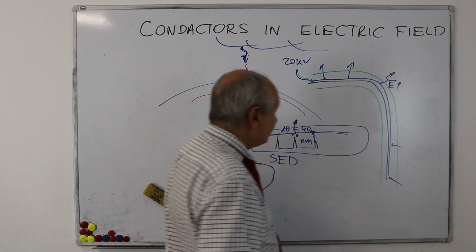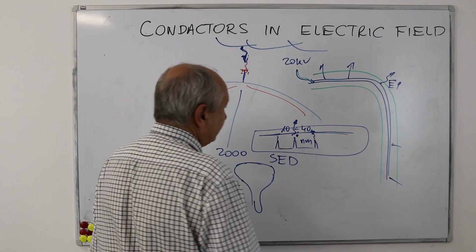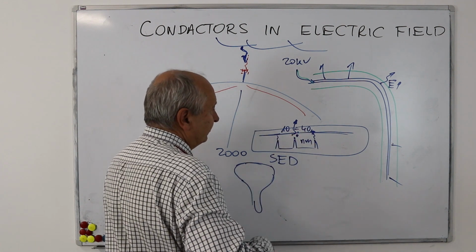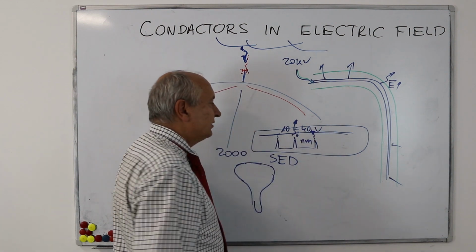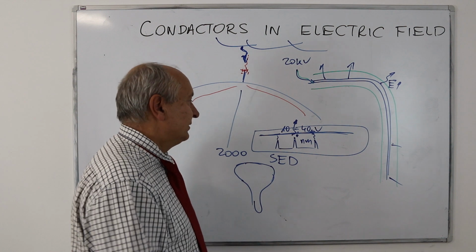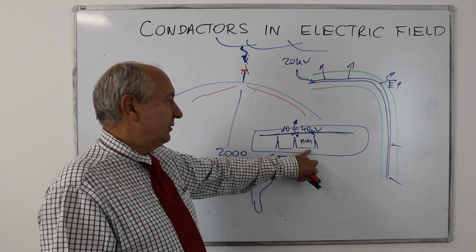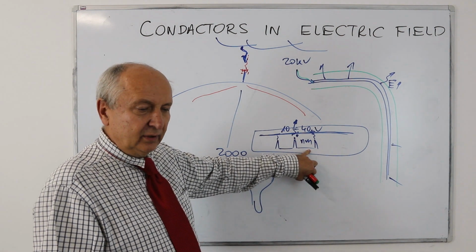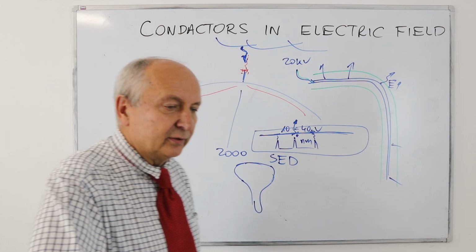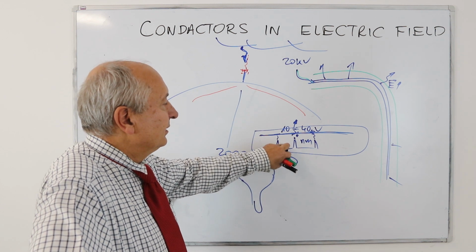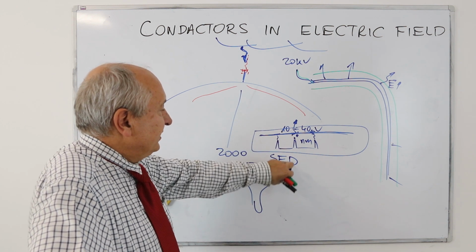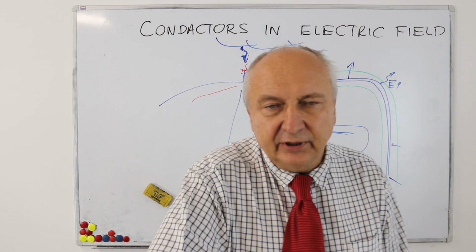At the time, etching technology achieved big progress, so we could obtain these very narrow peaks, and with a voltage of 10 to 40 volts we obtain the emission of electrons. When the electron falls down on the luminophore, we have a pixel of light. This display has very good contrast, not available for another kind of display at this time, and a refreshing time smaller than 1 millisecond. And it seemed that this would be the future for TV, for displaying.